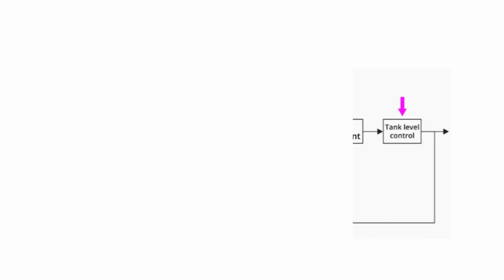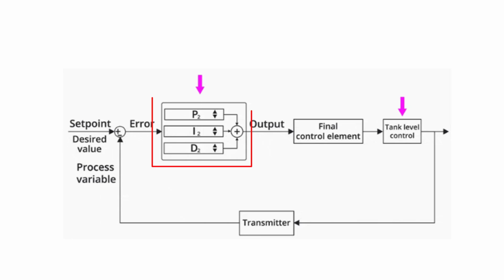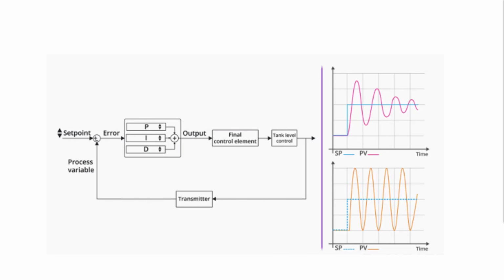Controller tuning is the act of correctly setting the controller P, I and D values for specific process requirements. There are many manual methods of controller tuning. One is by increasing the amount of set point change and repeating the procedure until the process enters a state of steady state oscillation. This method produces good results, however, it is not practical in many applications.